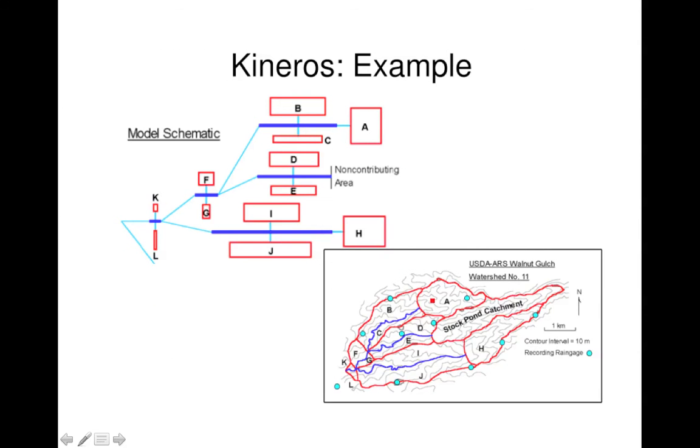So your catchment might physically look like this, down the bottom right hand corner, but in the model you would discretize it as something like this, as catchment B, which is connected to this channel, and catchments A, B and C are all connected to that channel, right? And you end up with flows being routed through. So it's a semi-lumped, semi-distributed hydrological erosion model.